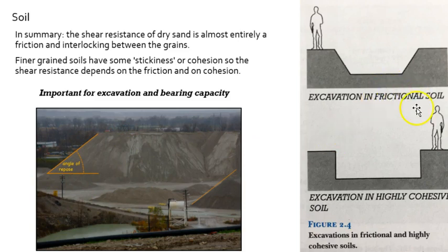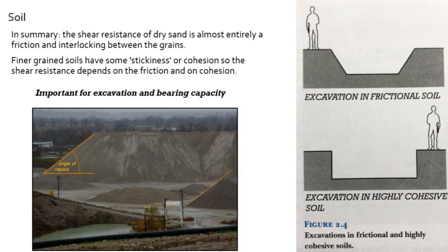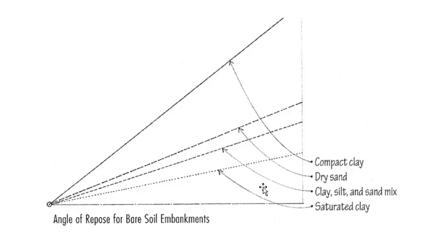Here we see the frictional soil that requires a shallower angle, and then here with the more cohesive soil, we could cut that sharp edge. The soil allows that to occur and will stay intact safely. So this is a concern for the excavation of foundations.